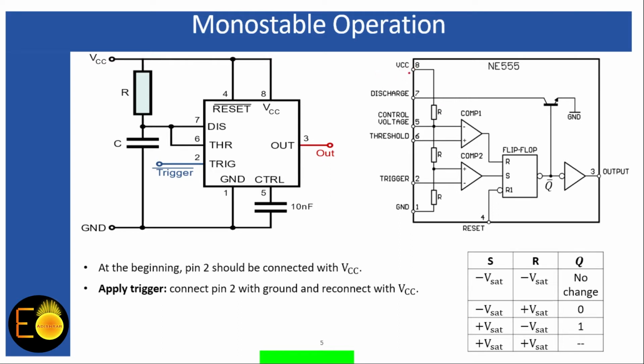So when you connect plus VCC to pin number 8, you are going to get 2/3 of the VCC at this particular node and 1/3 of the VCC at this particular node. And it's very easy to understand, because if you assume VCC is a battery, and one resistor R, another resistor R, another resistor R. So this is R, and this one is R. This one is one node and this one is another node.